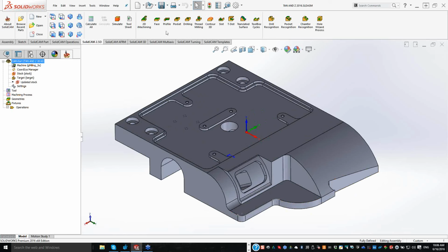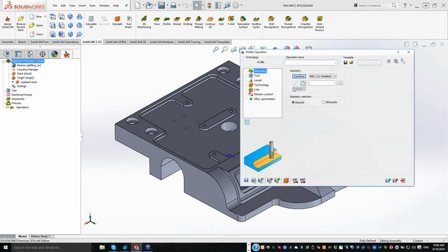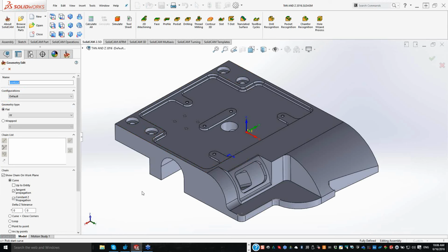To do this easily, I'm just going to use the option of Profile, Geometry. As I've shown before, we have our tangent propagation as our default and constant z propagation as well. If I were to click on this edge over here, you'll note that it goes all the way around over here. It's both constant z and tangent here. At this point, we have our tangent going up over here, and then back constant z. Same thing going down over here.